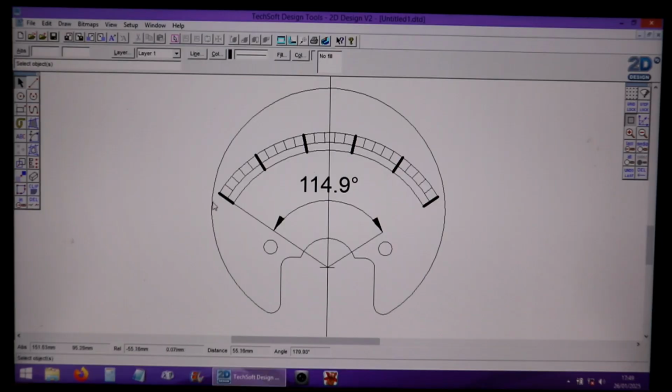Because I forgot to delete the original thin lines underneath, they still exist. And that doesn't matter at all if you're going to print this, the gauges, but if you're going to laser cut, it does. So let's just delete those before we forget. So I'm just going to select each of these shapes. I know they're not as long as the originals, and I'm going to press delete. What a fool I've been. As I say, if you want to print these, it's great, but if you want to send it to a laser cutter or something, it will see them as an additional line and cut them all out twice.